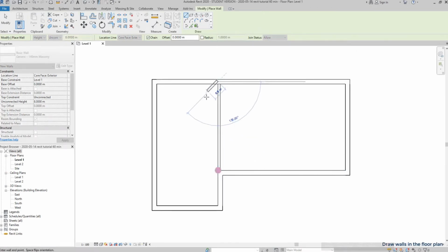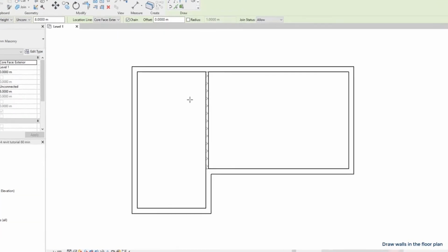The wall that divides the left part into two rooms is going to be 3.8 from this wall. One way to draw this wall is to go to the corner at the end, drag the mouse to tag the distance, write the amount and place the wall.